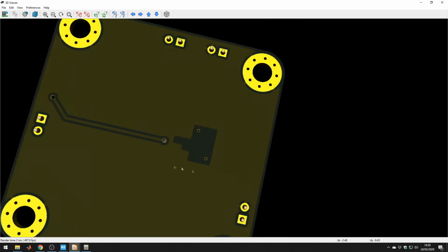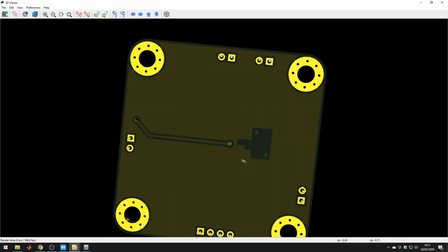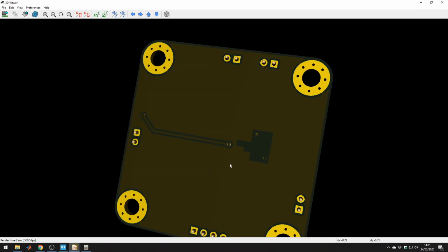So stuff like this. The problem we've created here is that there's this whole ground copper layer here, but there's only very small connections on this side, here and here. It's not ideal. On a 2-layer board, this could be quite problematic. You want to keep these kind of disconnects as short as possible. The thing is, we're using a 4-layer board, so we've got a whole dedicated ground plane anyway, and we can be a bit more relaxed about these kind of things.